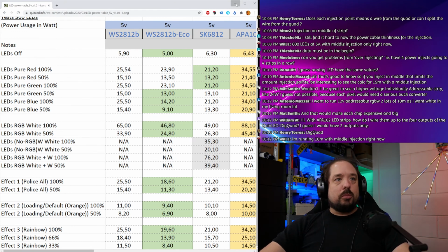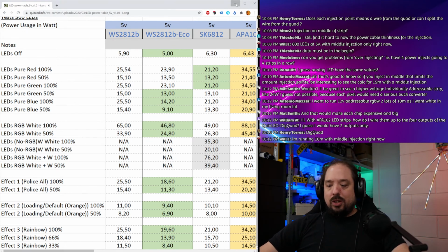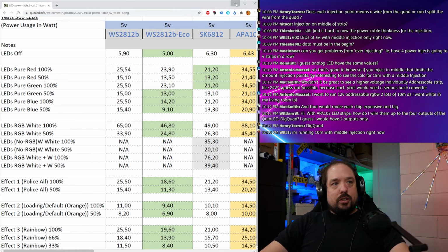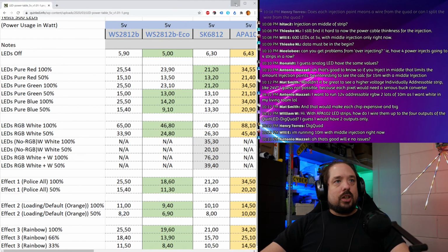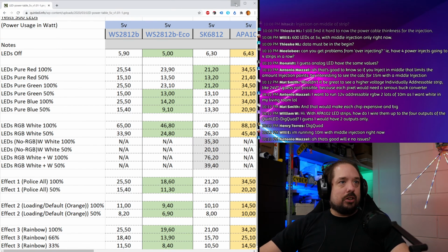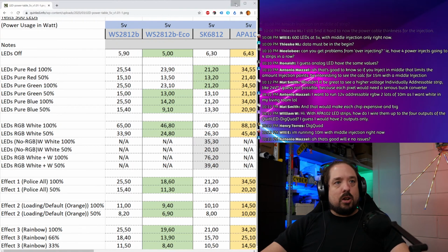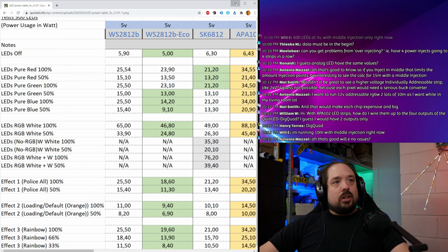Okay. Now let's go to C, and we want to do 10 meters of LED strip. Let's divide that into 30 LEDs per meter and 60 LEDs per meter. Now, max power is 65 watts, because this is 2 times 150 LEDs, and for the other, max power is 130 watts.